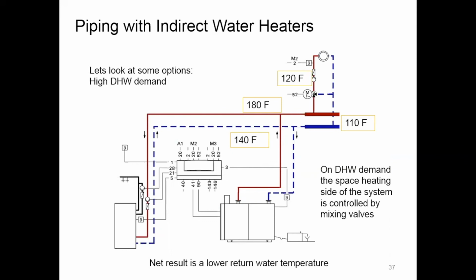In most cases, the space heating load has a much higher flow rate than the domestic or the pool heating load. And the return water temperature is usually skewed more towards the heating load side of things. All of a sudden, let's call it 120 degrees, the boiler's running at 90% efficiency. Nice thing about motorized mixing valve packages, they usually have a very short payback period. Let's call it maybe about 2 years for the mixing valve to pay for itself. Very effective at driving boiler efficiency.